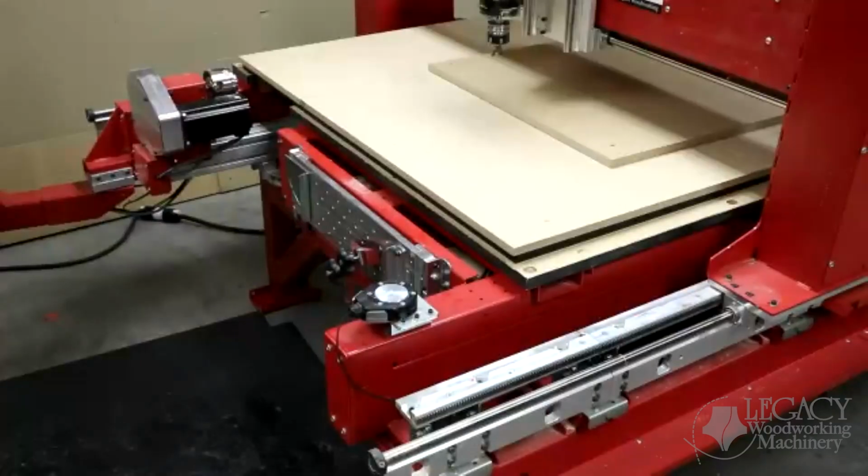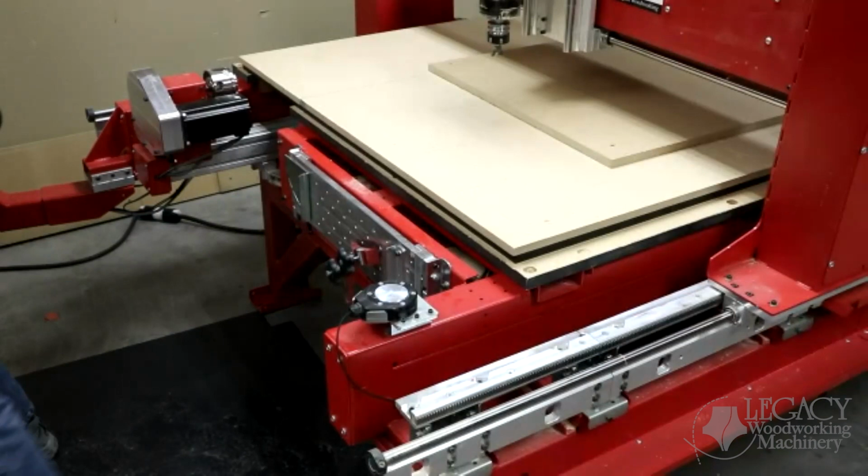Okay, so the next thing I want to go over real quickly is just exactly how the smart tool works, because you have 2 different ways that you use it. One is we call it multiple tools, and that's typical. So, in fact, I teach everybody when they're first starting to always touch off for multiple tools. If you do that, you'll never go wrong, as long as you've got the smart tool either on top or the bottom, wherever it's supposed to go, however you programmed it. Okay, so multiple tools.